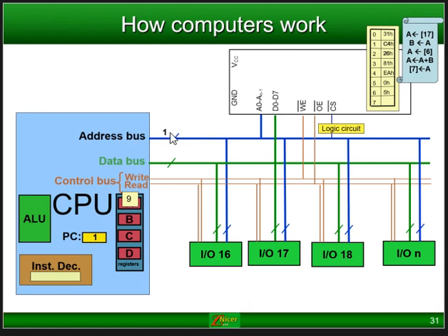Now the address bus is loaded with 1, which means now we want to get the next instruction, which says copy the value of A into the register B. So let's see if that's going to happen. Again, the read line will be pulled low. The instruction, which is C4, will be placed in the instruction decoder. And as you can see, that 9, which is sitting in A, is copied to B. So A copied to B. So the next instruction was executed now.